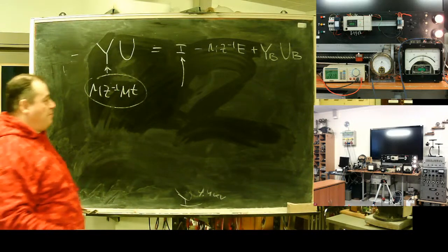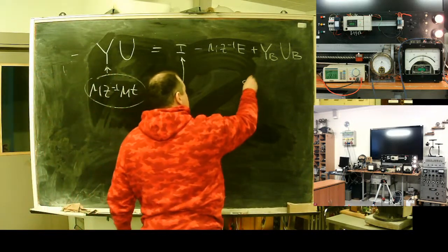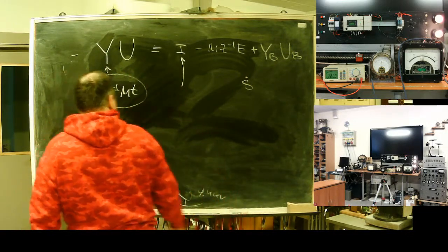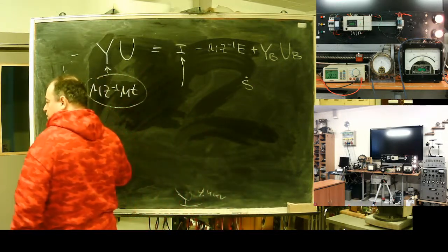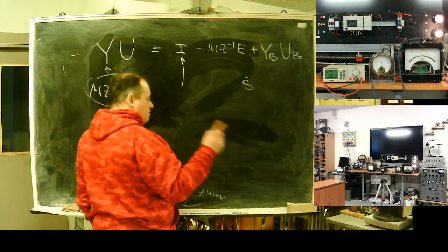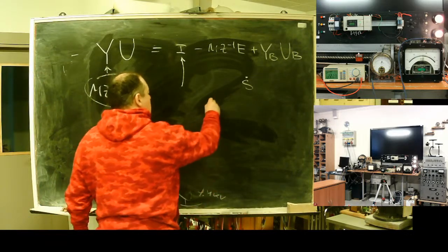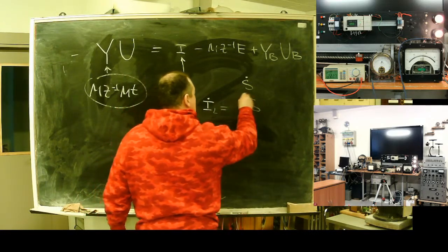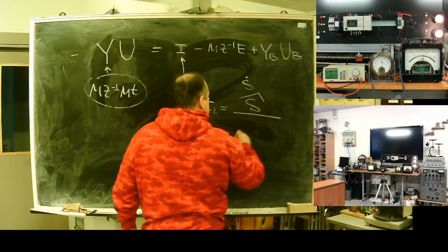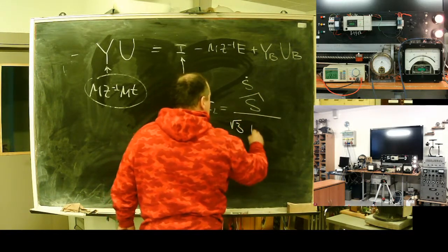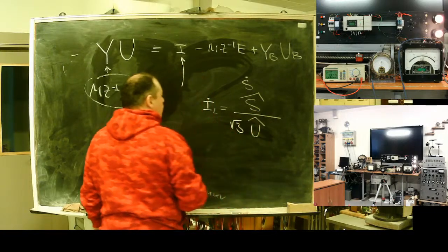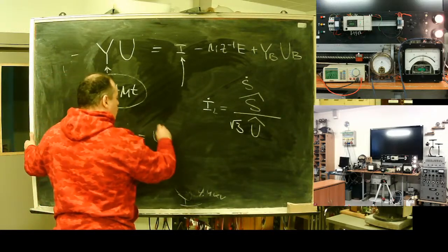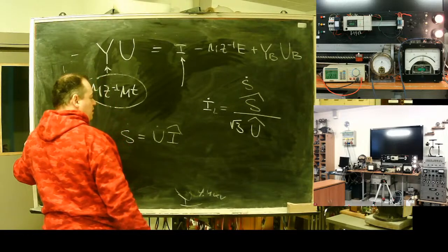We have a power vector of power by nodes. What can we write? We can define first, current of the load will be conjugated load power divided by square root of 3 and conjugated load voltage. Why? Actual power is voltage by conjugated power, current.